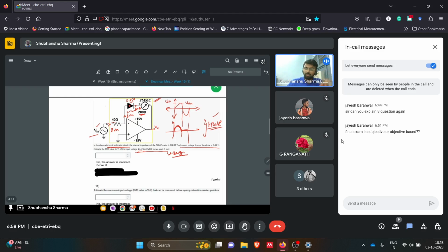So you have to see whether the circuit is full wave or half wave, and based on that you choose your formulas. Now let's calculate V input. The 8 milliampere is obviously the average value of that current. We know V in is at 0 volts because of the virtual short, this is ground.